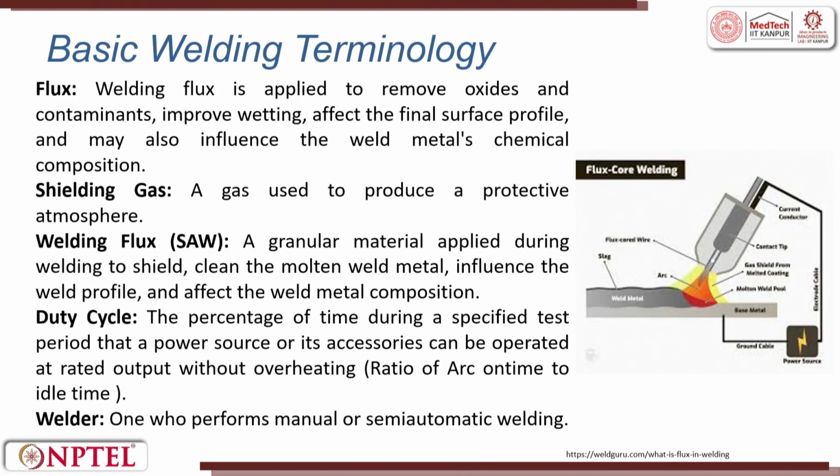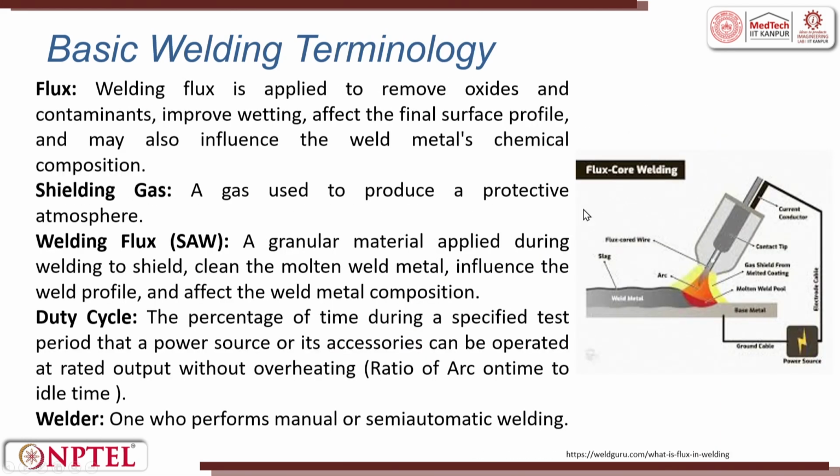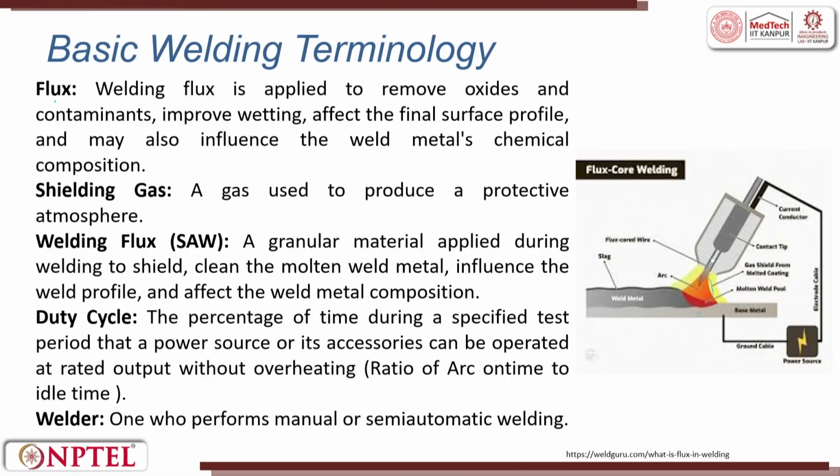Once the arc length and the welding arc are established, the portion where the melt is will be exposed to the atmosphere. When it is exposed to the atmosphere, it can react with the gases in the atmosphere. So, what you are supposed to do is shield the melting zone. What we do is introduce a compound called flux.